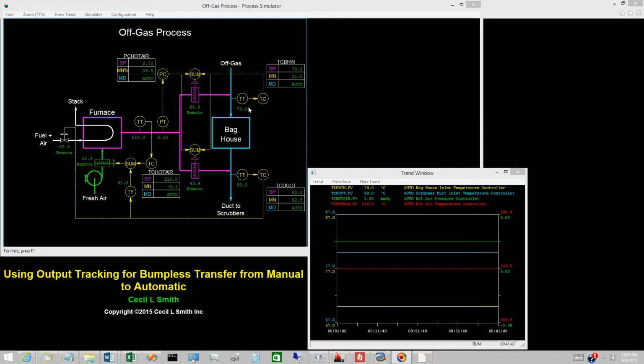Implementations of output tracking differ from one process control system to another. One approach implements output tracking under the hood. When tracking is required, a PID block receives a track request that is accompanied by a numerical value for the controller output. An alternate is a what you see is what you get approach. The PID block provides two inputs that must be configured for output tracking. The simulator configures output tracking in this manner. Despite different mechanisms, the actions performed for output tracking are exactly the same.